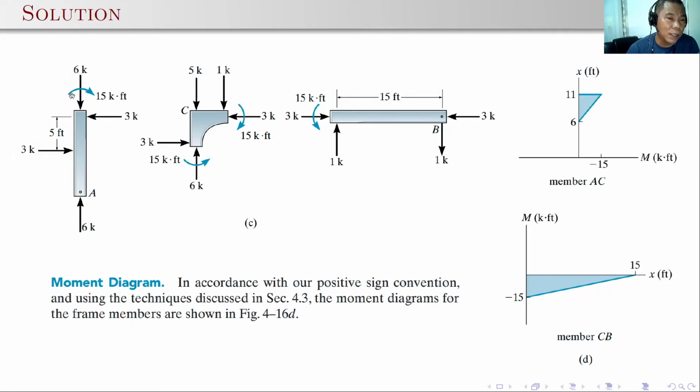After knowing these forces and moment that will equilibrate this segment, we can now transfer them to joint C. So we have 3 going right, so it should be going left, and the 6 kips downward should be upward, and the moment clockwise should be counterclockwise. And these forces and moment should be in equilibrium also with the other forces. The external force is 5 kips, so we have 6 kips minus 5, so there should be another 1 kip. So that 1 kip should be transferred to segment CB.